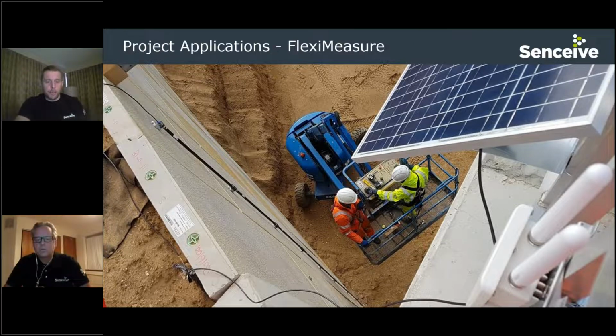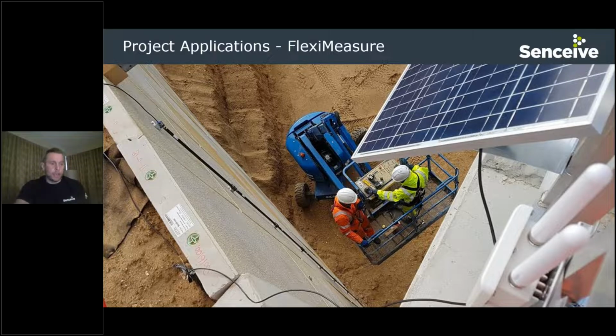In this case, it's obviously on a wall, but you can also mount this structurally on the top of a tunnel to measure any settlement or heave. It can go around the inside of a tunnel to measure convergence or divergence, or along a bridge if you wanted to measure settlement that way, or on pillars, anything like that where you need either lateral or vertical settlement or heave detection.